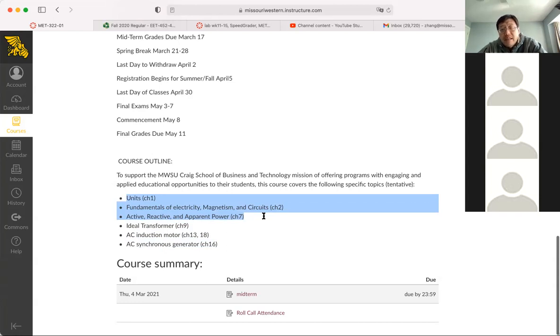Once we have the KCL and the KVL, we can apply them to any circuits, including AC circuits. And by applying them, we can create a bunch of equations. How many equations we can create depends on the circuit. Generally, we want to create enough equations to get the problem solved.